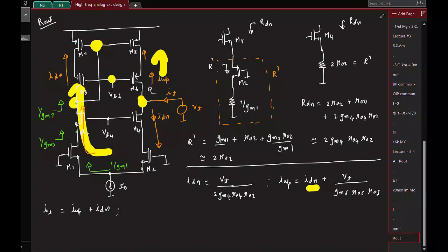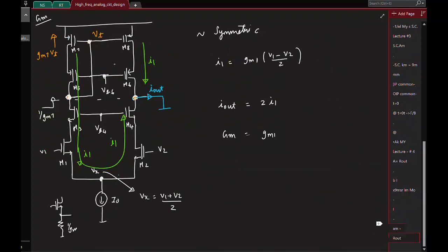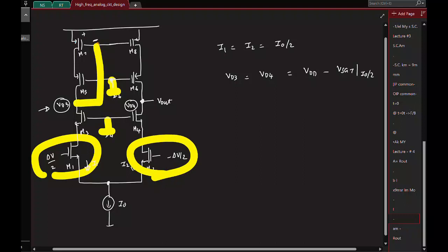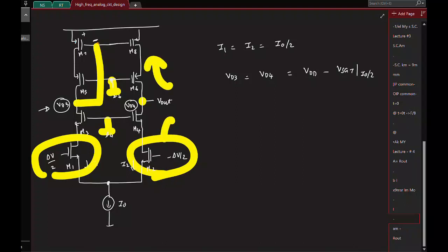Okay. See, in the actual amplifier, not all the gates are incrementally grounded. Only this gate is incrementally grounded, that's all. And these two, we have the diode connection here that is still active, okay? And this is converting the voltage to the current, and the output resistance you have is this. Is that fine, or does it answer your question?